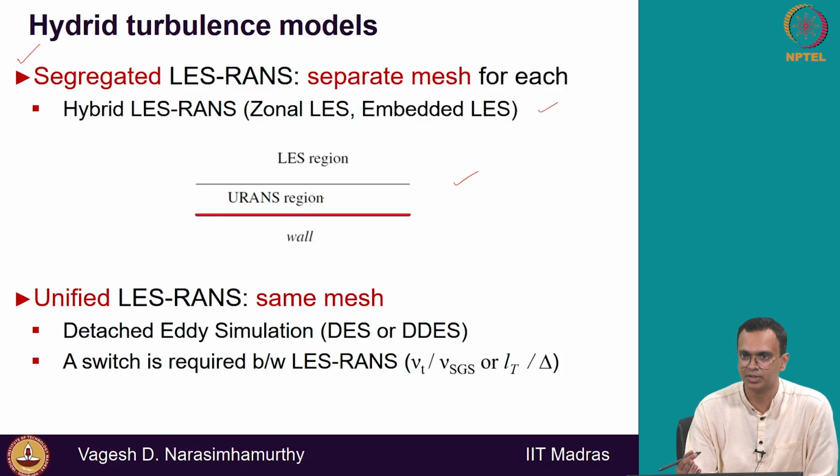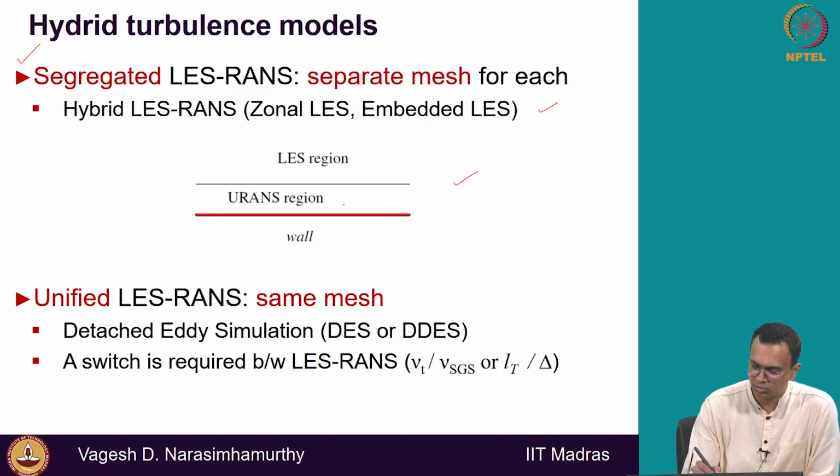Okay, but the RANS equation always has an unsteady term, so URANS and RANS are the same. So basically you are computing near wall as a RANS zone, and then somehow you need to switch to an LES above into the outer layer, you can say. Okay, and that is of course a challenge, because there is always a mesh here, right, where that switch must happen.